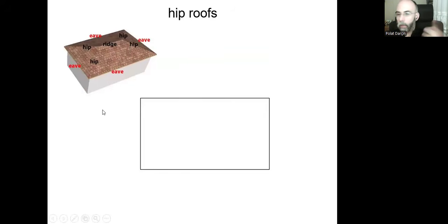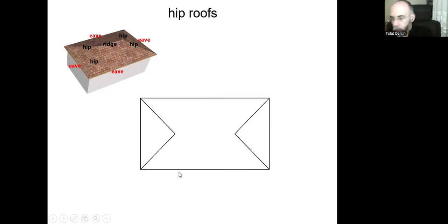First, we start by drawing the eaves, and then as the second step, we need to find the middle points of these angles. These are all 90-degree angles, so the middle points will give us the 45-degree. So we need to draw these inclined lines for 45-degree angles, and they meet. As they meet, they can go in a straight direction, like this one here, which will represent the ridge point.